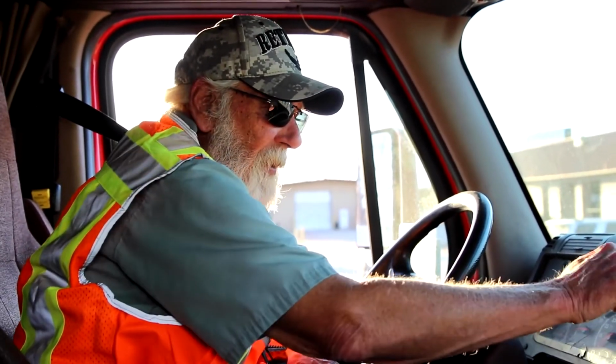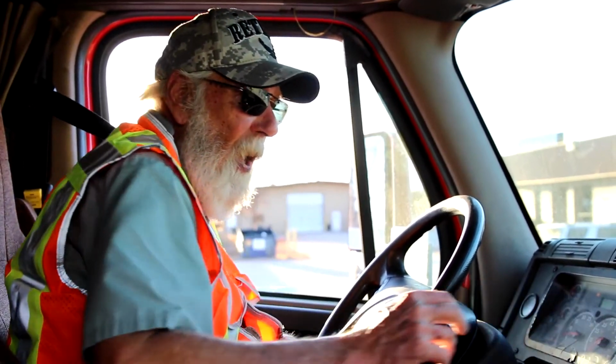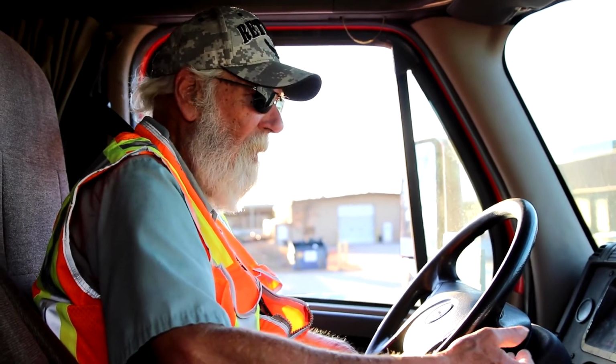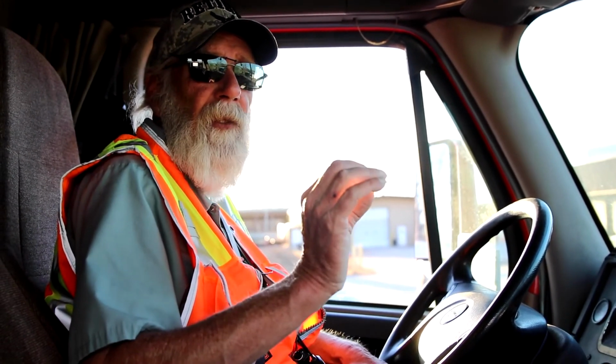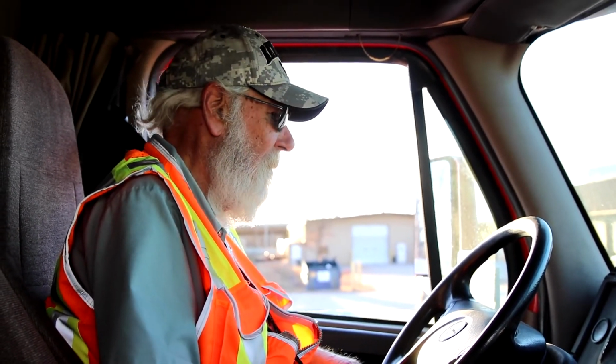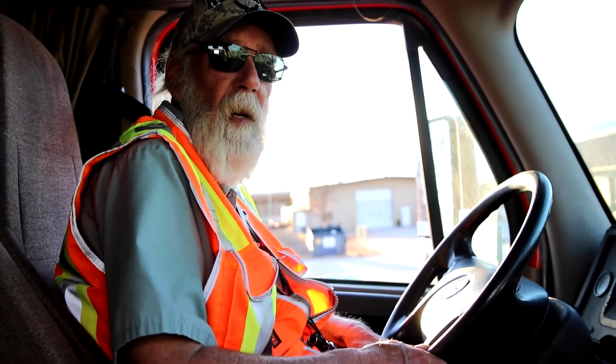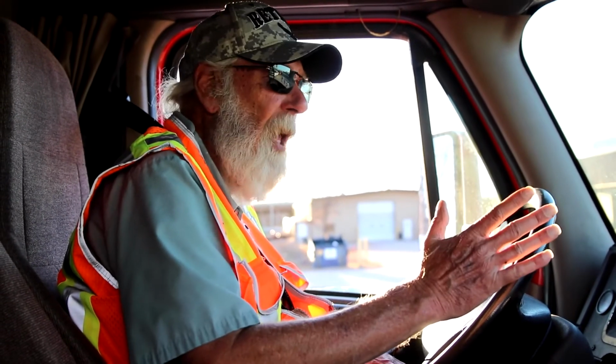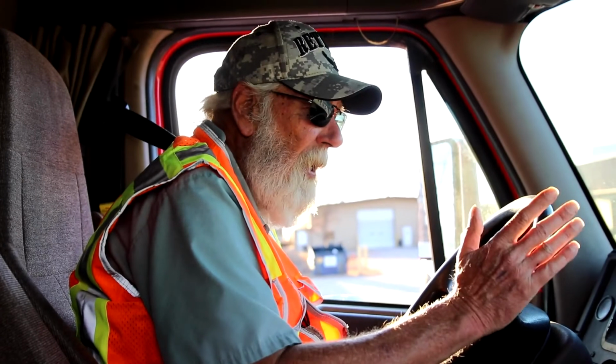Now, pull out your red knob, push in the yellow. Let the air hiss and go through the system. You're going to do another tug test against your locked trailer brakes, and again, the vehicle should not move, so give it a nice light tug. That is acceptable. Vehicle did not move.